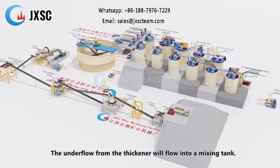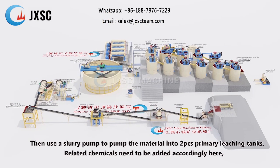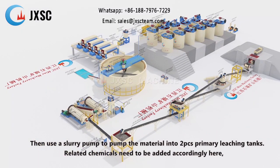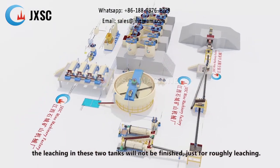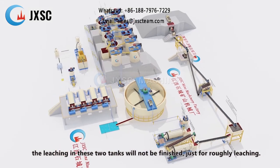The underflow from the thickener will flow into a mixing tank, then a slurry pump pumps the material into two primary leaching tanks. Related chemicals need to be added accordingly here. The leaching in these two tanks will not be finished, just for rough leaching.